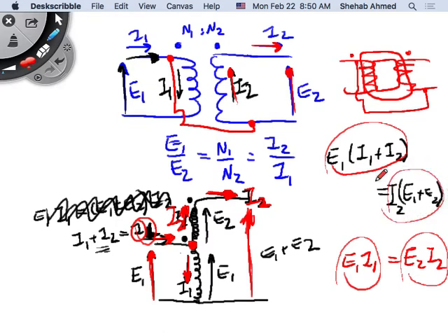But what did I do to the power that I'm able to transfer through this device? It increased. But what did I lose? So I increased the power for sure. I mean, the power I can push through this transformer increased. So now I can step up voltages, and I'm doing the same job, right? I'm stepping up from a low voltage to a high voltage, which means I have to step down the current.